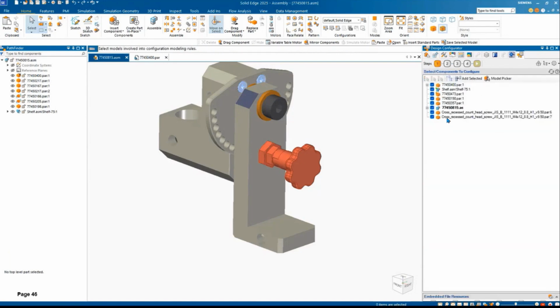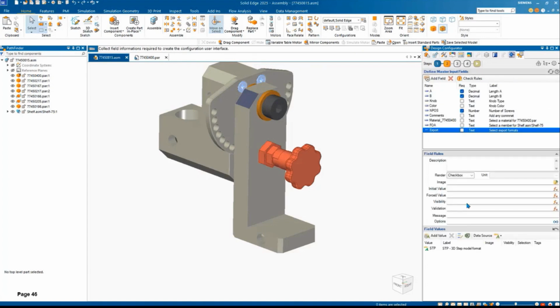And the last quick action is where you can export any given file into a different file format. So here I have this entire assembly, which I can export as any of these options here. I have a STEP file, JT, Parasolid. I can use any of these options here.